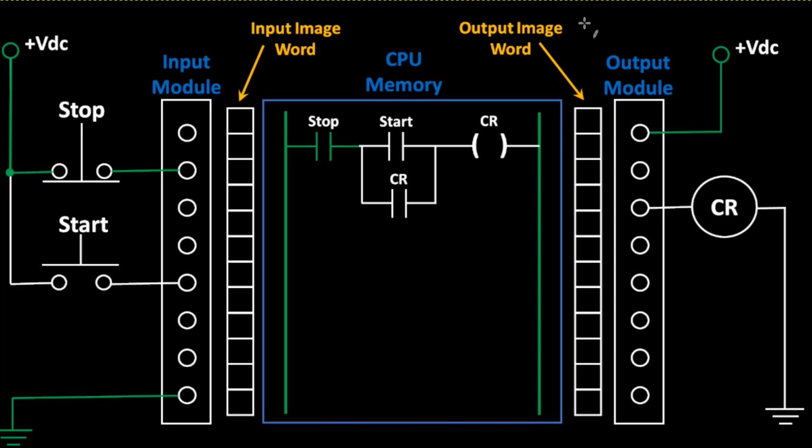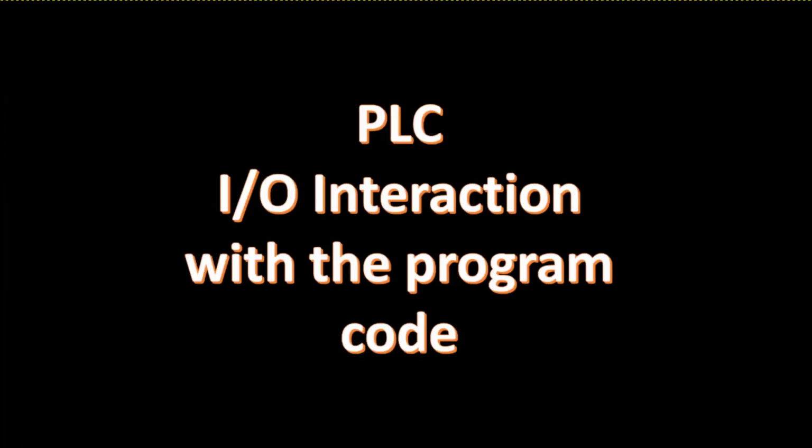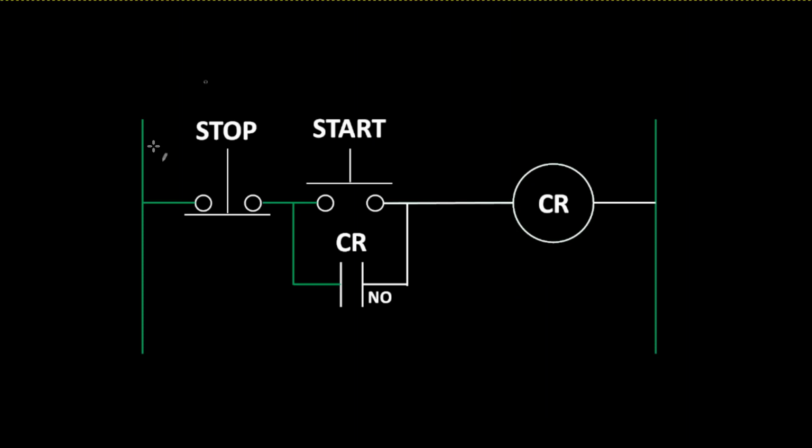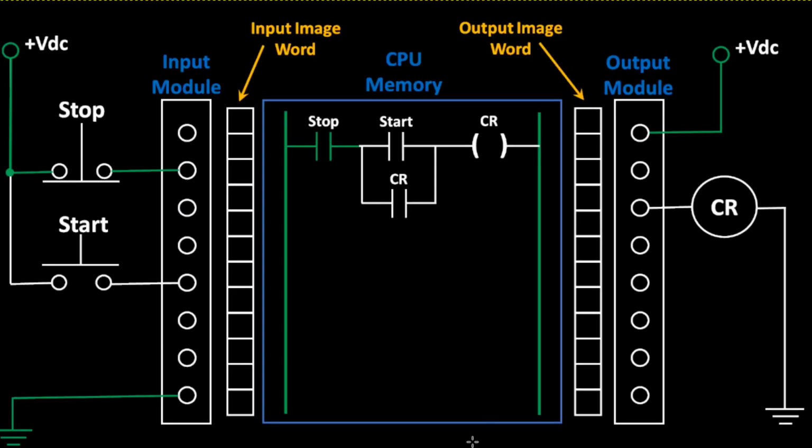Now, when we built this in the lab, we looked at my field devices, and if I go back to this drawing, we looked at the field devices and said, okay, I'm going to program this now in the PLC. And in the PLC, you said this should be normally closed. So we programmed it as a normally closed switch. Only to find out that when we finally downloaded and ran this program code, it didn't work the way we expected it to work.